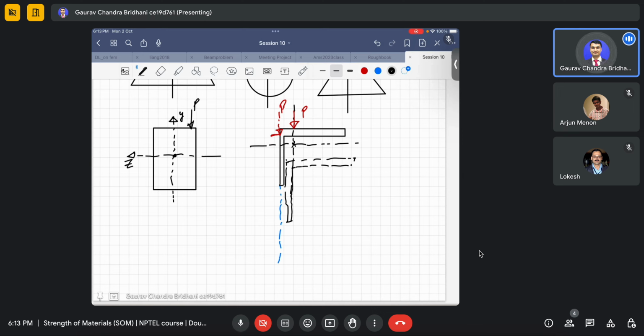So it bends in x as well, in y as well as z here. This is your z, this is y, correct. Here the loading you applied on the centroidal axis, but the issue is the centroidal axis is not a symmetric axis, so it will cause unsymmetrical bending.